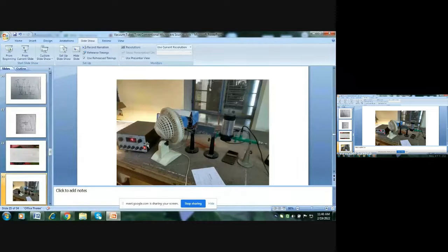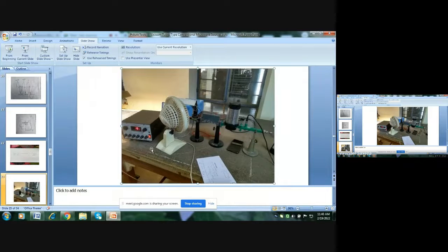This Klystron power supply, as you have already read about that, is used to energize the Klystron in proper mode. Means first we apply maximum reflector voltage, of the order of 240 volt, and then we increase the beam voltage up to 300 volt, and then we will reduce the reflector voltage to get the desired modes in the Klystron.